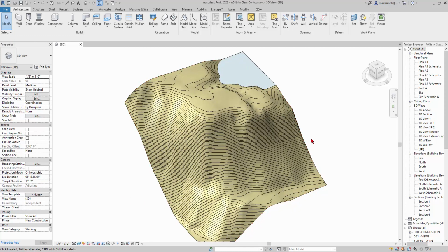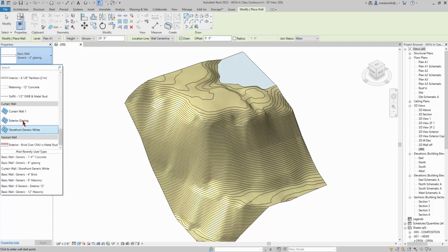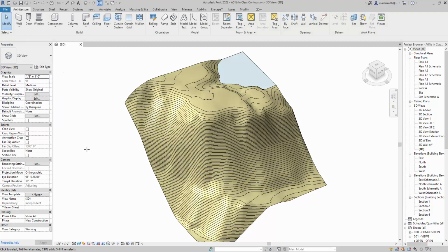I want to now transfer some settings from another file that I gave you into here. We're going to transfer wall types, stair types, and some materials. So just to give you a quick example, if I go to wall architectural in here and I go to the pull down, kind of far down are my curtain walls, and I only have 3 kind of curtain walls, and I would like to give you a curtain wall that we're going to use in the building of the project. I'm also going to give you some stairs and some materials as well, and then we're going to import some doors.